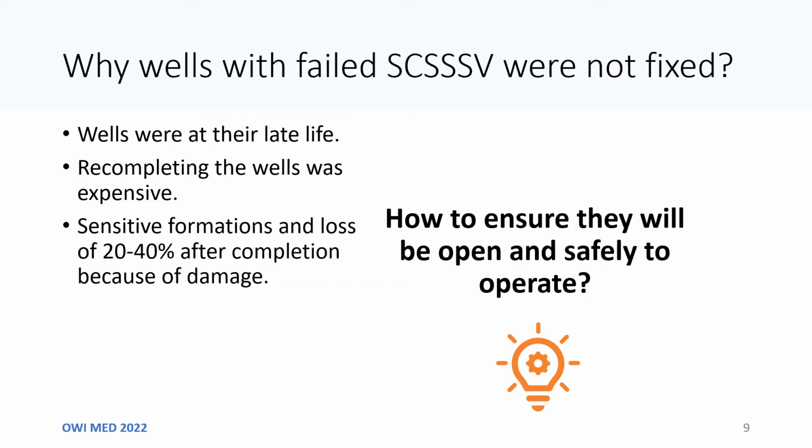To answer this question, we need to conduct a study that involves dispersion modeling of the worst case scenario, where the well is producing against atmospheric pressure because of the loss of the Christmas tree, for example. The dispersion model will give us the safe distance in terms of heat and in terms of H2S for which people will be safe.